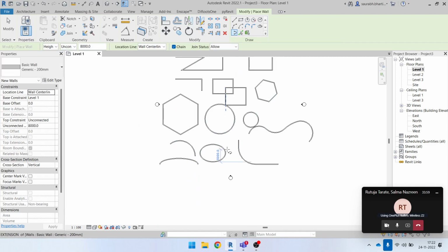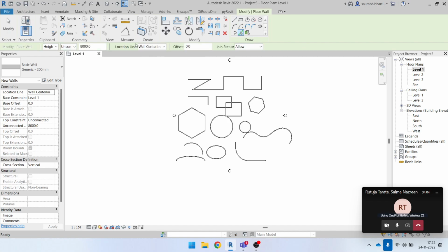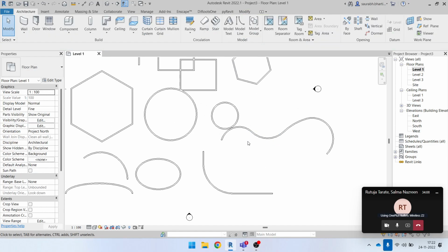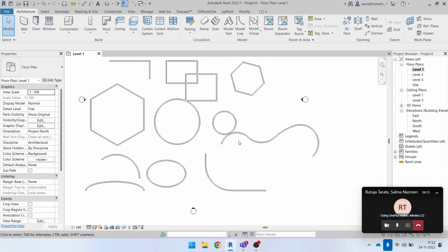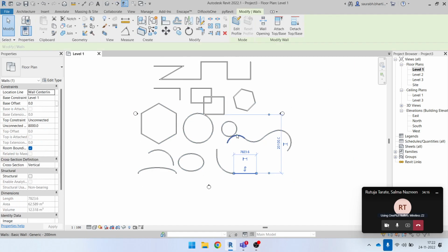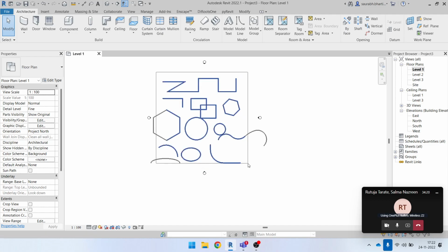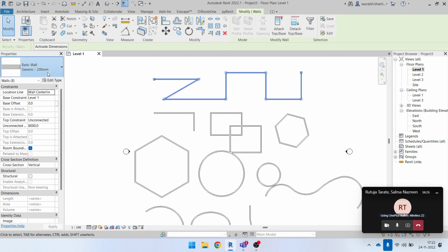And then you have pick lines. So if I use the pick line option, okay, wall thickness, this all wall is like 200 right now. If you want to change it, we can do it. So I will just after this let you know how to change the thickness of the walls. Like all the walls right here that we have is like 200 mm.